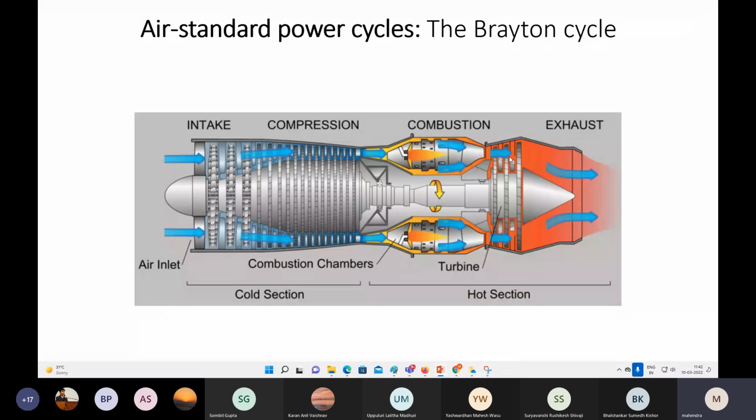The energy extracted from the turbine is equal to what the compressor needs to run, so that way we have coupled them. Otherwise, the maximum amount of gases pass through the nozzle. This nozzle is generating the thrust, and because of thrust your aircraft is moving. That is for a gas turbine applied to an aircraft engine.